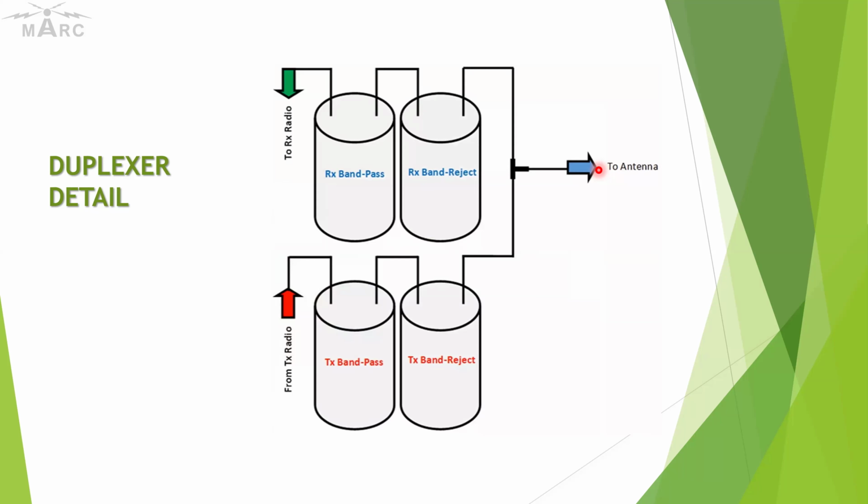So you have 222.360 as the radio's transmit, which is the repeater's receive. So this is 222.36, and he is filtering out everything except 222.36. He can't hear the 800 megahertz. He can't hear anything. He's only passing what the radio wants to hear. Okay, so that's what the duplexers do at a high level.